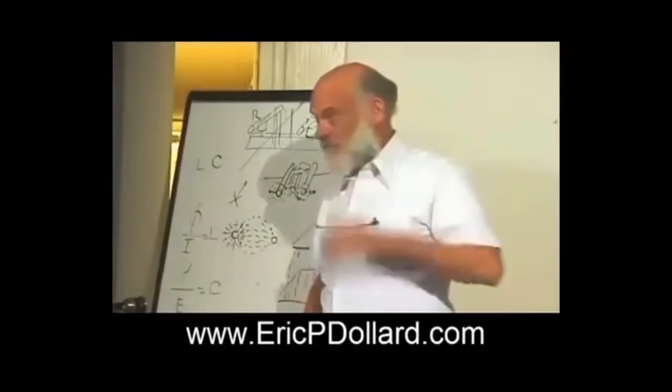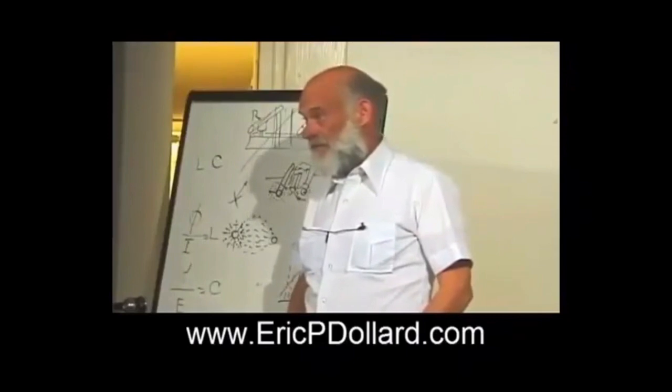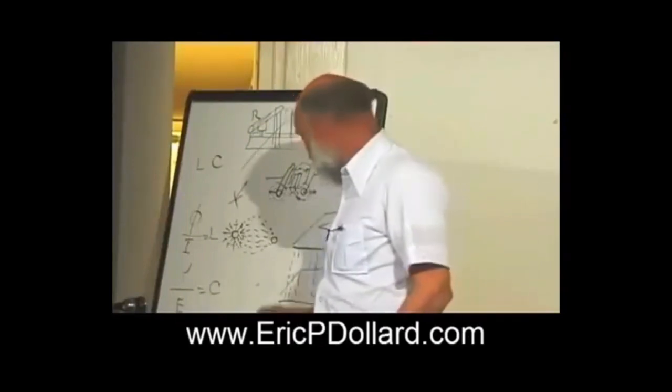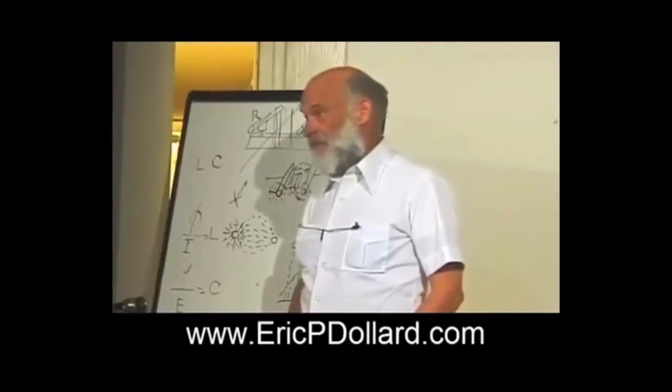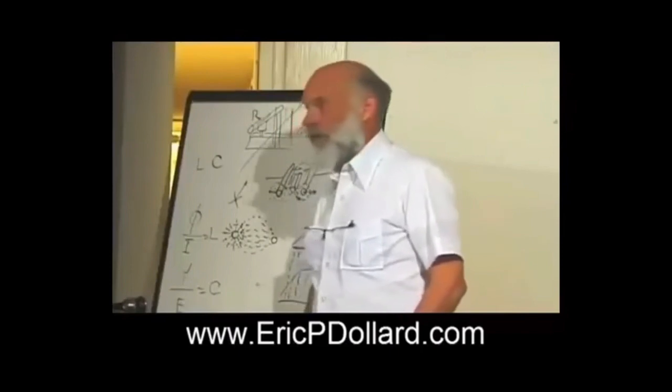Yes? Well, the thing is, you mentioned the cathode and all that. Now, if you have no voltage across the anode and the cathode, and you have the heater, because the cathode is a thermionic thing... No, this is a cold cathode. Well, the cold cathode is a different thing. There's two phenomena that make the cold cathode work. One is it depends on ions. Ions hit the surface of the cathode, and then electrons come off. Well, sputtering, that's after the breakdown.